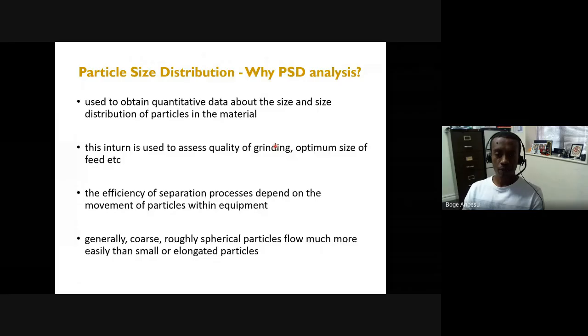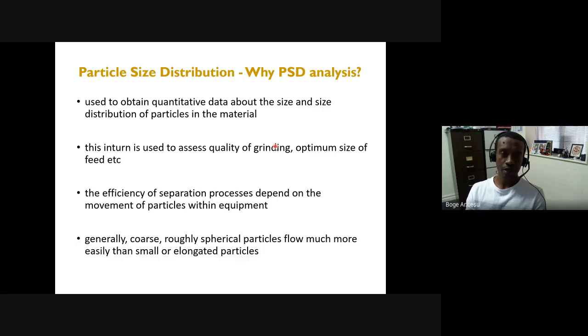Okay, so what is another consideration in this unit? Yes, eventually we want to do particle separation, valuable from waste. But before we even get there, we need to do, as I said, proper level of grinding. Unless you achieve proper grinding and you have liberated a sufficient amount of particles, your separation is going to fail anyway. Your beneficiation is not going to be successful. So always it's better to achieve the required particle size based on the liberation studies you have done.